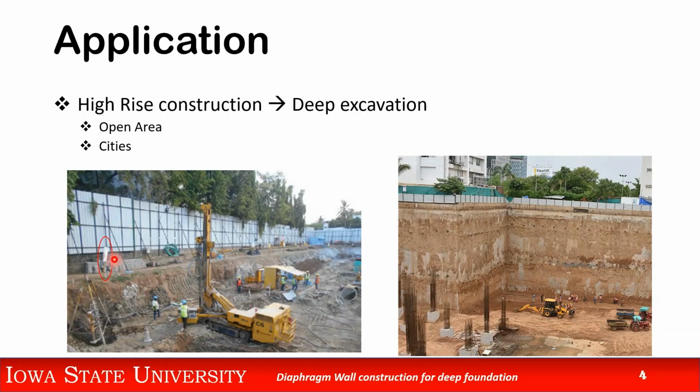And to lower the groundwater table, the hydraulic pumps are installed on the periphery, as you can see here. So you lower the groundwater table, that reduces the lateral pressure caused by water, and then the only pressure which is there is soil weight or pressure because of the soil. And if the soil is good enough, then you don't even need a retaining wall. And I have so much space here. As my foundation is happening here, I have the availability of space. I don't need a retaining wall.